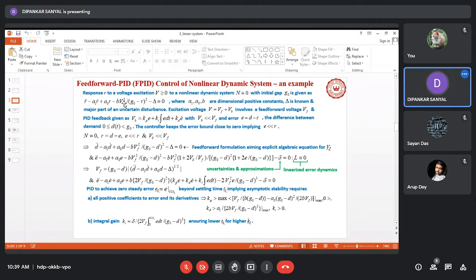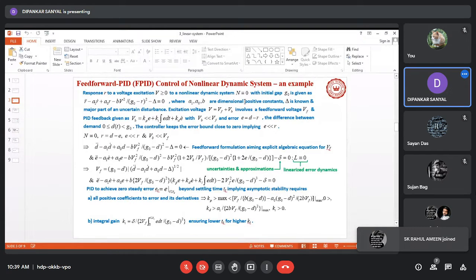If this solenoid is actuating a spool valve, then this delta will contain all the flow force components, and as we know, the flow force we compute in terms of some lump analysis. Lump analysis means we consider a particular velocity of the cylinder piston, and based on the motion of the cylinder piston, we assume a constant discharge, and the discharge divided by the opening of the meter port gives the constant flow velocity with which, in the form of a jet, the flow enters through the metering ports.